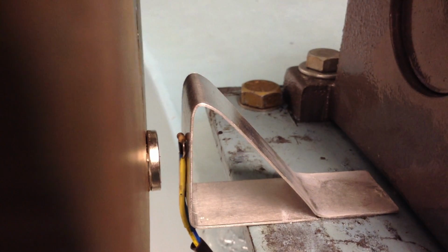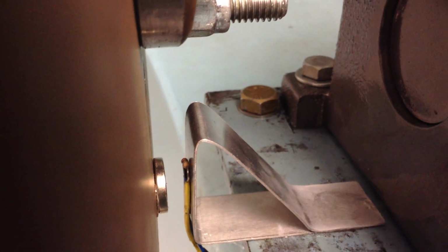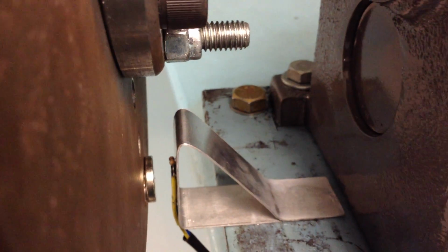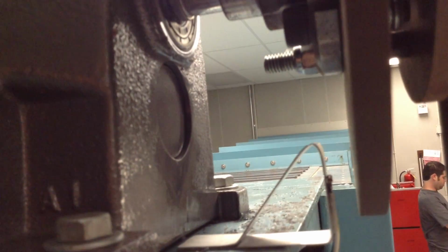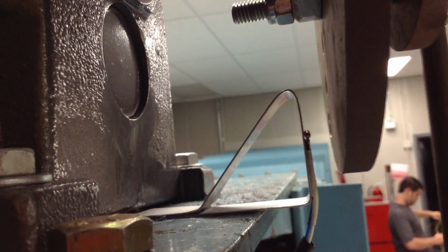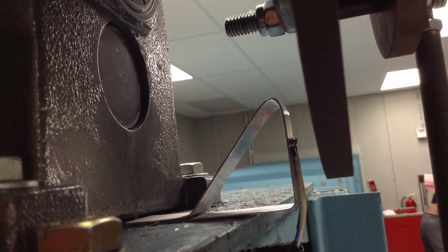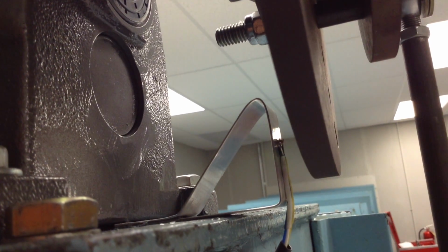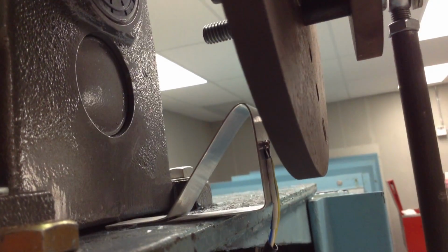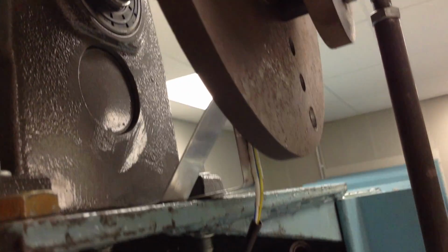A similar example of this is a light switch, where it can be either on or off. This means that the signal's voltage is changed from low to high when a magnet passes by, just like a person flicking the light switch on. If the north pole of a magnet turns the sensor on, then the south pole of the magnet turns the sensor off, and vice versa. When the US 1881 is triggered, the output signal voltage will be equal to the source voltage, which in this case is 5 volts. When it is unlatched, it will drop to ground or 0 volts.